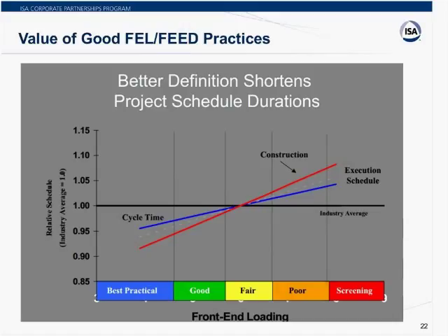And inherently, high-performance graphics are layered. Once you get the layering right, navigation between the different graphics and layers becomes more important, and so does the ability to summarize alarms up so that the operator's attention is drawn to where he needs to take action, both on the current graphic as well as some ability to see where they need to navigate to in the graphics system to get to where they need to take the action. I don't know if that answers the question exactly, but that's the best short answer.